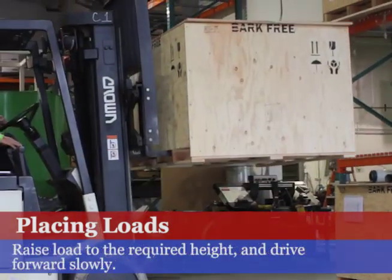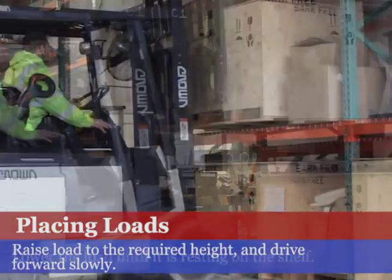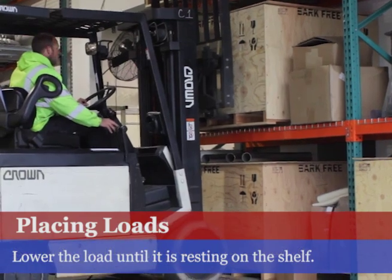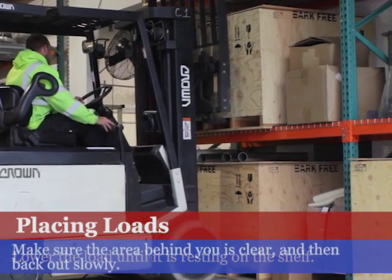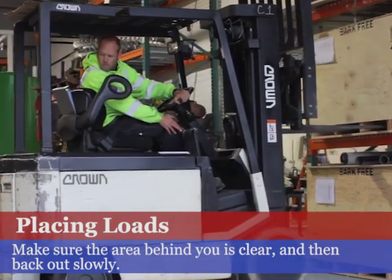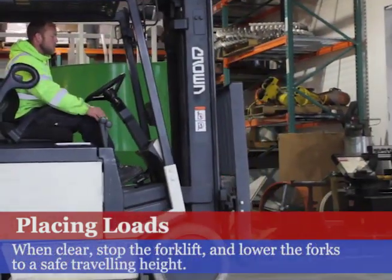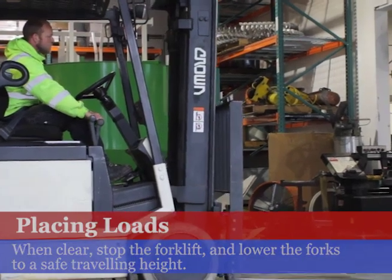Raise the load to the height required. Drive forward slowly. Lower the load carefully until it is resting on the shelf. Look behind you to make sure the path is clear, and then back out slowly. Once the forks are clear, stop the forklift, and lower the forks to a safe traveling height.